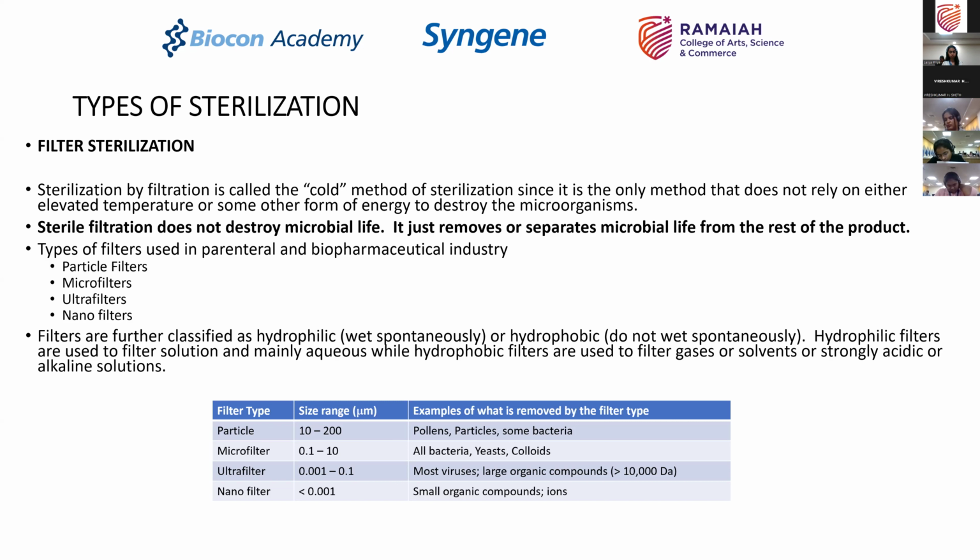Filters are then classified into hydrophilic filters and hydrophobic filters. So, as the name suggests, hydrophilic is something which wets spontaneously, hydrophobic is something which does not wet spontaneously. Hydrophilic filters are used to filter solutions and mainly aqueous solutions, while hydrophobic filters are used to filter gases or solvents or strongly acidic or alkaline solutions.